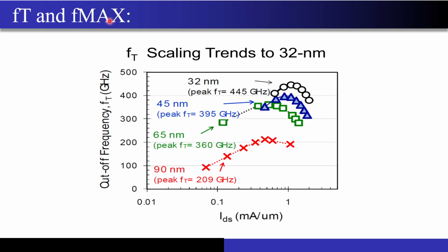So you cannot get an arbitrarily high number for a fractional bandwidth. Usually it is limited to 10 to 20% of the center frequency, correct? So that is why higher the Fmax value is, higher will be the center frequency where my radar can operate, and higher the center frequency, more the bandwidth I will be able to get from the radar. More the bandwidth that I am able to get from the radar, very high quality images I will be able to generate from my imaging radar.